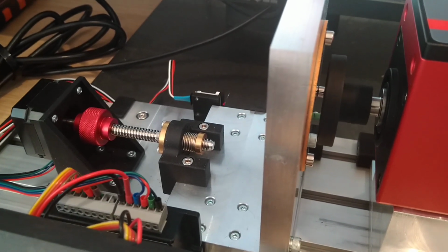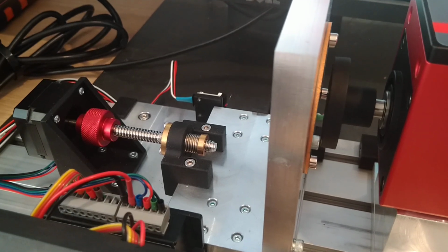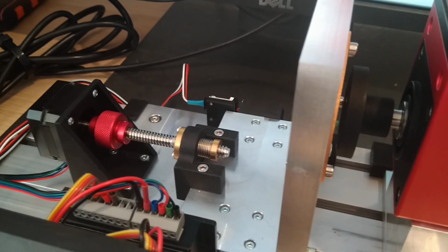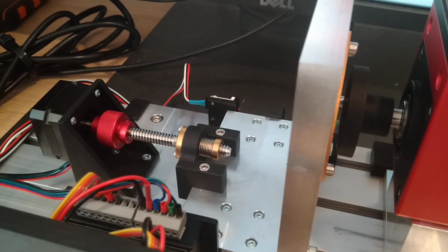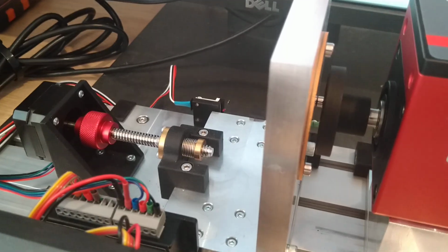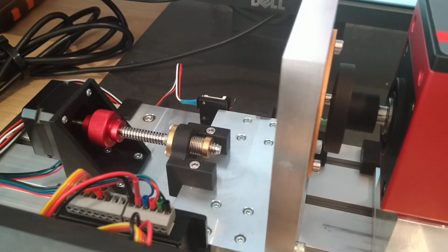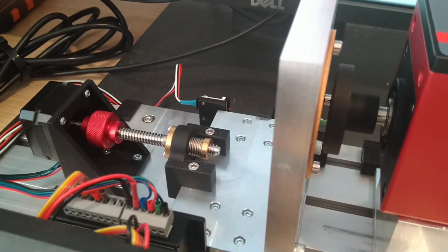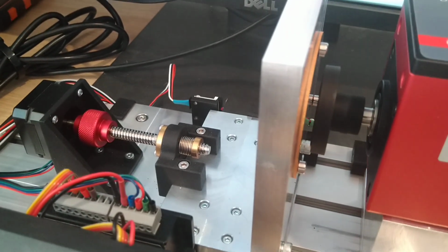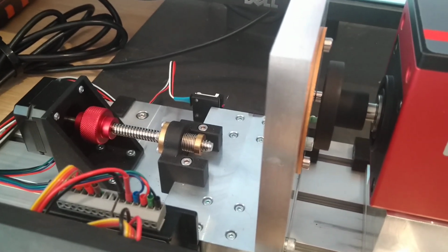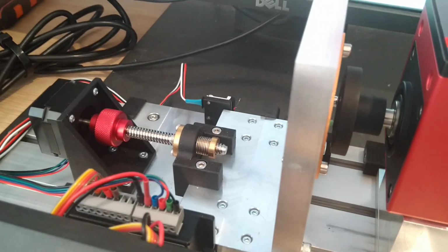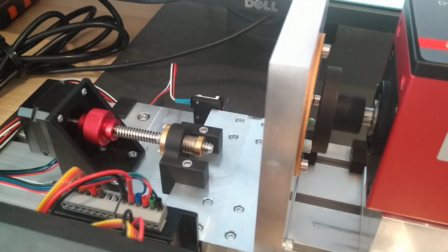So you can see that this algorithm with really small tweaks, essentially associated with geometrical parameters of the rotors, can equally efficiently and reliably maintain constant torque in the range from 20 or even 2 milliNewton meters all the way to 20-25 Newton meters. And there is no reason to believe that we can't even push it further up, as well as down to the very small, like 20 millimeters micro size rotors meant for testing really small micro motors, for example, for aviation or for some micro robot actuators.